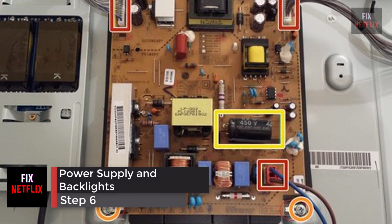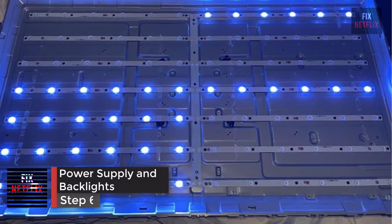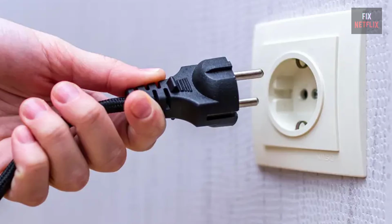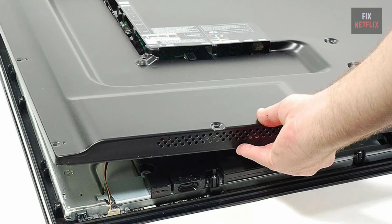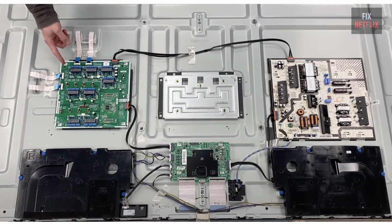Step 6. Power supply and backlights. You can check the power supply and the backlights in one swipe. Make sure the TV is unplugged. Open the back. You may need to remove the base to access all the screws that hold the back on.